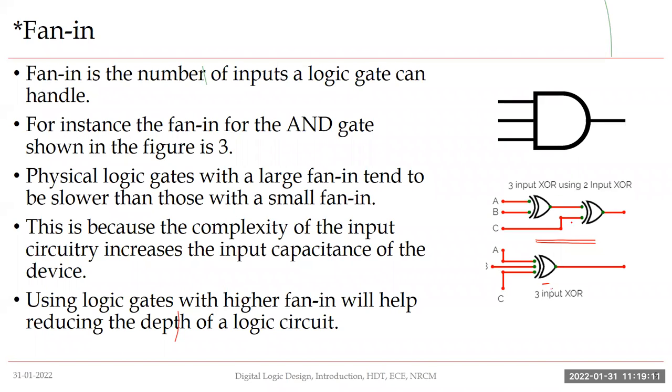More circuits will take more area, more power consumption, and so on. However, making more inputs can increase delay, capacitance, and other factors. So you cannot always have infinite fan-in; you have to optimize between the two. Of course, higher fan-in helps reduce the depth, that means the number of levels required to implement a logic. However, there are complementary factors such as speed and power consumption that we must consider.